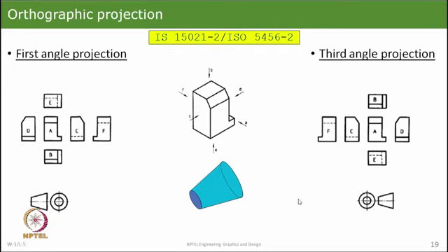For third angle projection, we put the first view over there, but what we saw from the right, we have drawn on the right. These two pictures put together as a single composite picture convey the information on the drawing. This drawing means everything is in third angle projection. So, nobody will write on any drawing first angle or third angle. Just looking at these, we should know how to read the drawing.